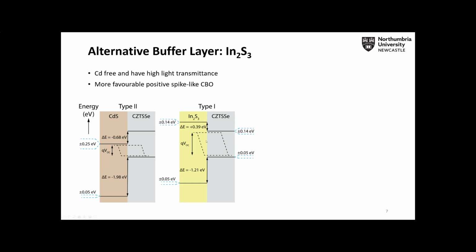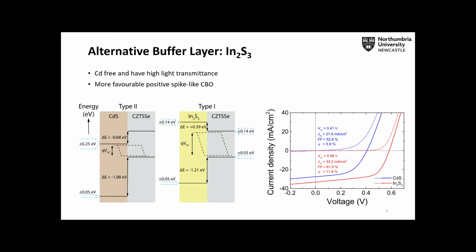So that should be given by that QVOC here. That quasi-Fermi level here reflects what our potential for open circuit voltage was. So we supported that by first initial simulation. The blue lines represent real devices of ours that we've modeled. That's based on using a cadmium sulfide layer, and we use defects that we know we have measured in our setup, in our material.